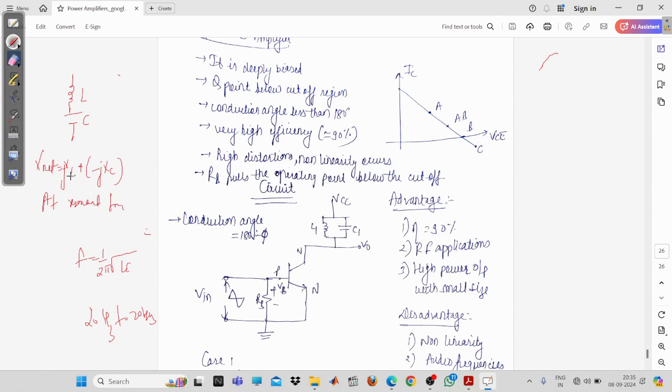So what is going to happen? These two values are equal. So at the resonant frequency, XL will be equal to XC. So this is minus J into XL. If you substitute the impedances, this is 0. So in a series resonance circuit, you will have a short circuit. This will resemble a short circuit at only the resonant frequency.